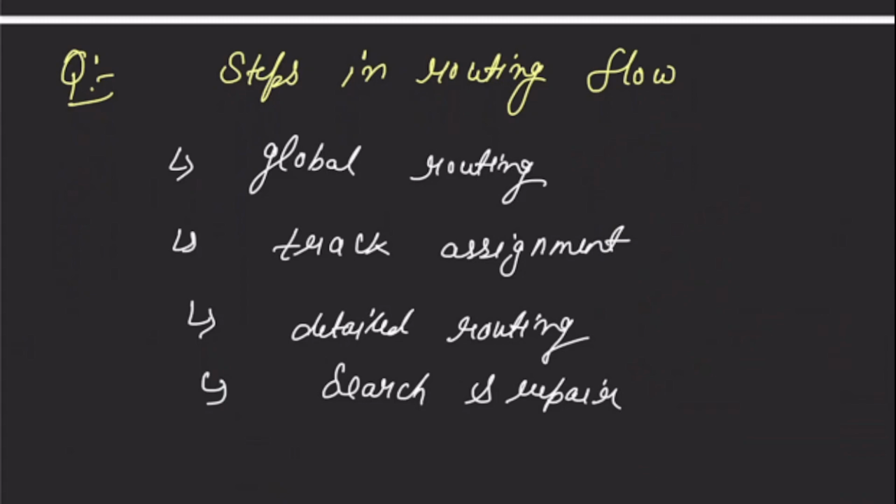And the number of routing layers that are available depends on the design also, and if the die size is greater than the routing track. Track assignment replaces all global routes with the actual metal layer. So there will be many DRC, signal integrity and timing violations that will come.